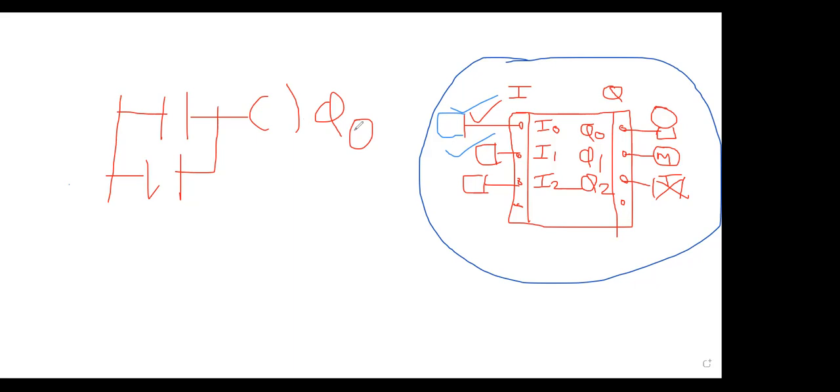Now I am the client, I shall check the interlock. I told you it should be on by a single switch. It means it should not be on by both switches. So if I operate both switches, what will happen? Tell me, text me. In OR gate, if I press both switches, I0 and I1, what would be the status of Q0?